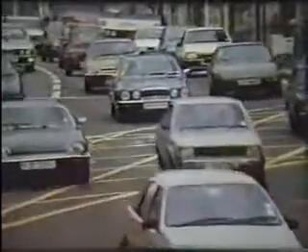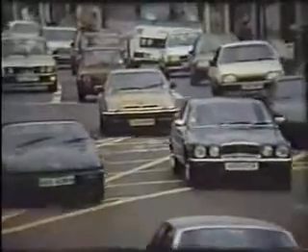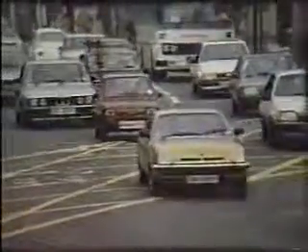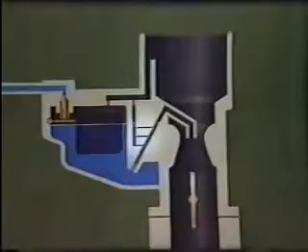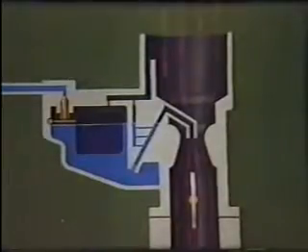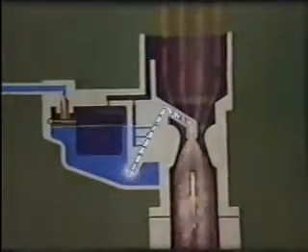And to keep the mixture in the correct proportions, more air has to be introduced. This is done by an air bleed, which restricts the amount of fuel reaching the engine by mixing in more air to maintain the correct mixture. The air bleed consists of special channels within the carburetor, and the flow of fuel through the main jet draws in the additional air.